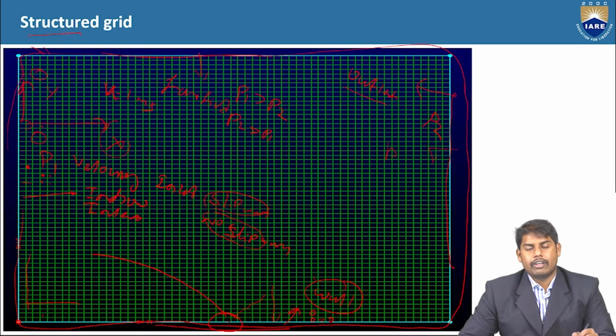Air will have, let's say, a uniform flow. Because of the presence of the flat plate, it will stop some fluid particles. So the pressure and velocity, and if it is compressible flow the density, will be changing. We need to capture the changes that are happening over the body because of the presence of the flat plate.